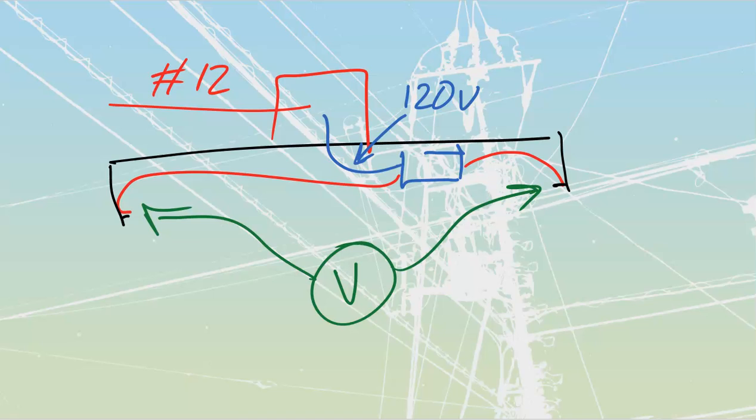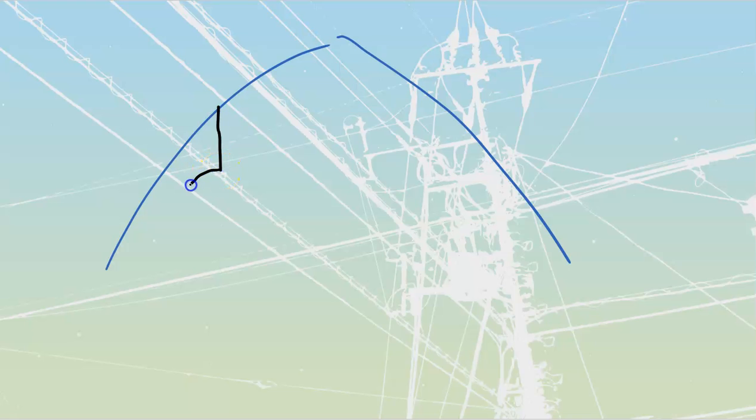Ballast location is also going to be a thing to watch for in their installation. We are allowed to have our ballast remote. You'll see this commonly inside of ornamental types of installations. Think about any place that has huge vaulted ceilings or a massive lobby or something like that. Then you're going to get these HID fixtures or fluorescent fixtures that oftentimes are going to drop down. They're what we refer to as UFO type fixtures, kind of these rounded ones like that. We oftentimes don't want to have the ballast in there because it's supposed to be a nice space. You don't want to have a big ugly box of a ballast above it.